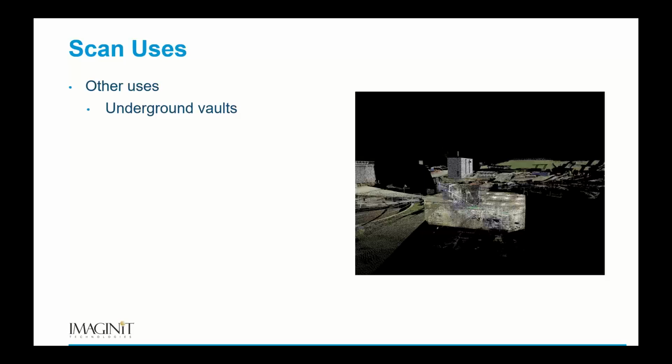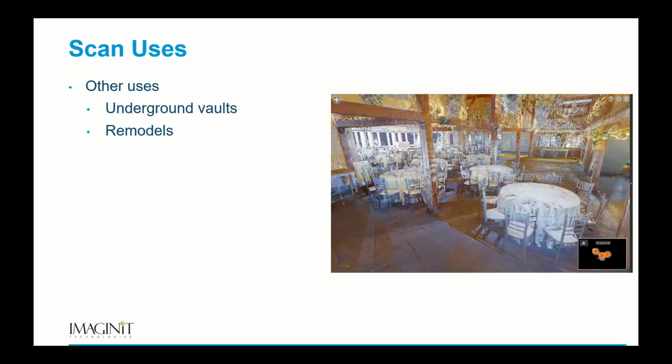And that doesn't mean just vaults. That could be tanks. You have to get a confined space permit to get inside of a tank. If the tank's completely empty, I can get an adapter, lower the RTC down, let it scan the inside of the tank, and use Leica software to do a tank analysis. Maybe that's something you are required to do and you've never thought about using laser scanning. Now you need to think about that. That is something that we are able to do.